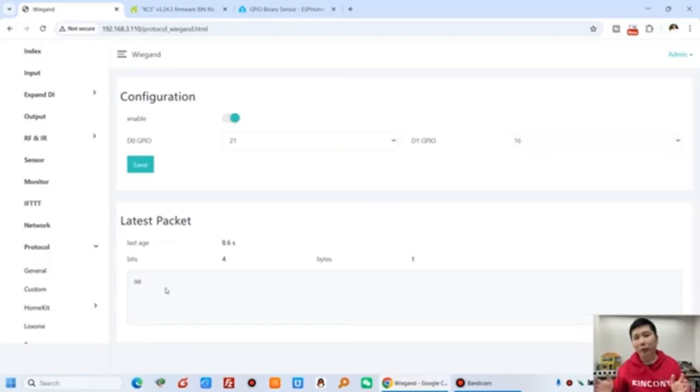But different products and different access control panels will output different signals. Some output Wiegand data on every button press, but sometimes it is set by the access control panel: you input a password, and if the password is correct, it outputs one key code. Or maybe you will use an IC card that outputs a Wiegand code. So we can use this code for IFTTT to make your own automation.